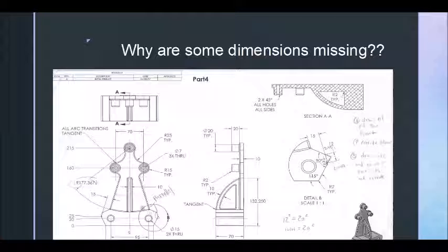Like, right here and right here, there's nothing that tells them that it's parallel. The only thing that tells it, besides me writing it here, is a little symbol that the program uses to tell you that there's a constraint, a relation saying that these two are related because they're parallel. So a machinist wouldn't be able to tell that. And so some of these, you have to be very careful.